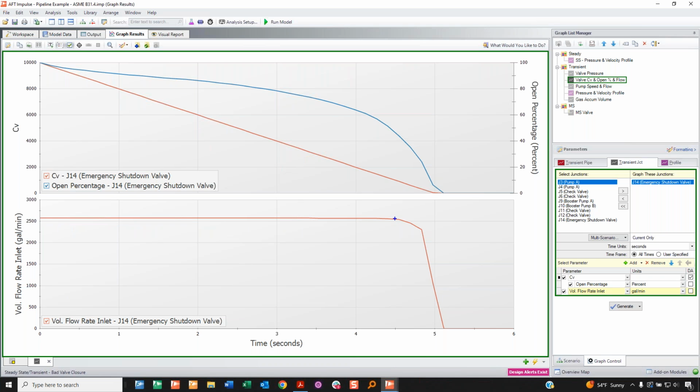We would call the effective closure time here about 1/2 second. So even though you're closing your valve in 5 seconds, really to the system, it's like closing it in 1/2 second. The effective closure time is very small here because it's such a big valve to begin with, or such a lossless valve. That matters when we go into how might we want to then have a better valve closure. Well, you might imagine then maybe we get down to a CV of 2000 very, very quickly because it doesn't do anything to the system.